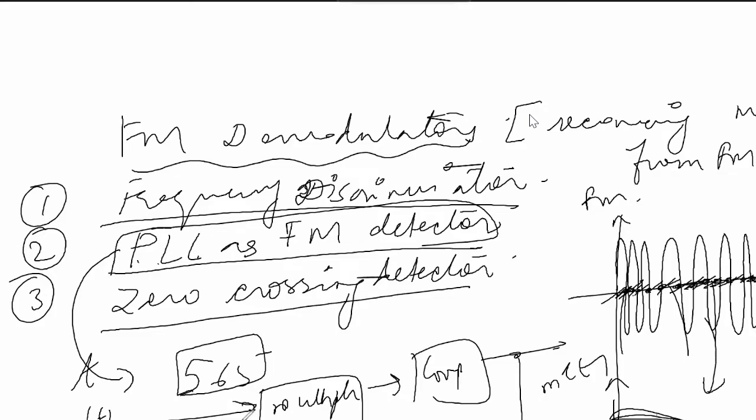So the FM signal is applied to a multiplier which is working as a phase detector, followed by a loop filter, and the output is fed back through another circuit called a VCO, voltage controlled oscillator, which is again generating a type of FM signal only. These are very vast mathematical analyses which I'm not going to do here. You have to analyze S of t and R of t and generate some equation E of t, which is called the error signal, which is applied to the loop filter. The output of the loop filter will be your output V0 of t.